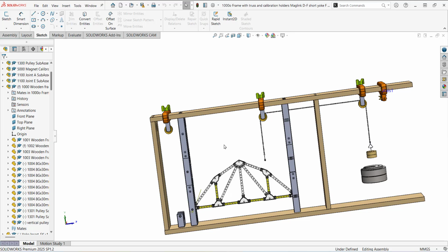As a result, no matter what force you are applying here, all you need to do is predict the case of a load of a different magnitude with the same direction applied to the same joint. All you have to do is find a proportionality factor, either a growing factor or a shrink factor, and apply that to your sample solution.